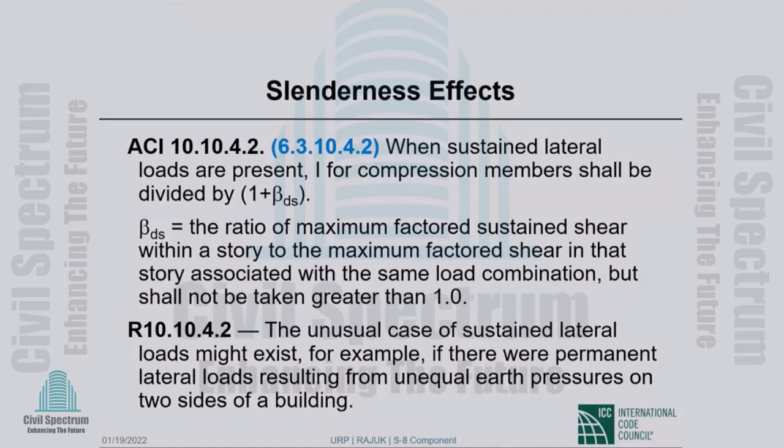Anyway, when sustained lateral loads are present, that itself is pretty uncommon. Lateral loads are typically due to the two big ones, wind and earthquakes. Both are transient. They do not stay in place. They are not sustained. The only sustained lateral load you can readily think of is earth pressure.